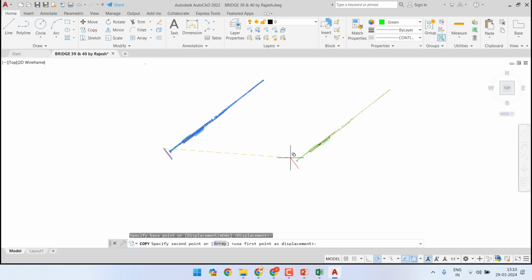here, and then basically we already have a solution, and we will get the slewing required at every station, the station number of the curves, and then we can compare the changes in distances from OHE. What was the OHE distances before, and what are the OHE distances after the desired slewing is effected, and whether it is acceptable or not, whether it is coming more than 2.8 meter or not.